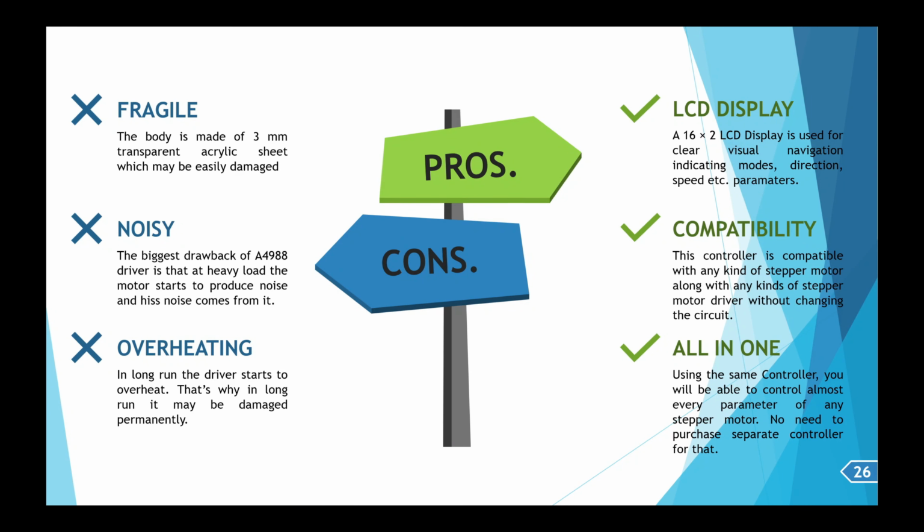One is the DRV8825. That is another more important and very well-known driver which is used to remove the hiss noise of a stepper motor. The overheating is the problem of the A4988 stepper motor driver. That is, in the long run, this motor driver overheats. I have already lost 2 of these drivers, and this is the third one that we are using. The IC of the A4988 driver easily overheats in the long run, and in high load, it genuinely overheats so that it can burn also.